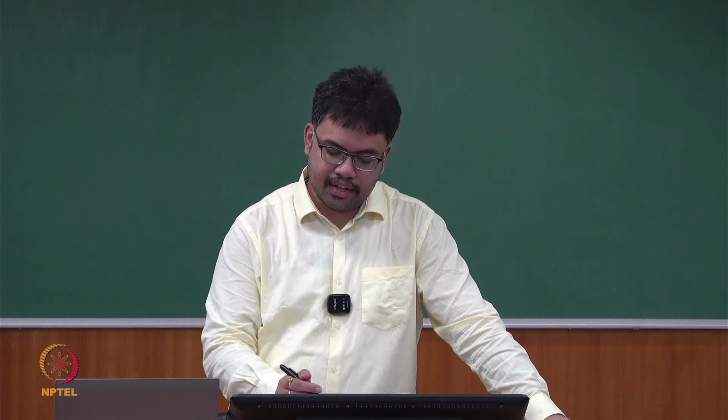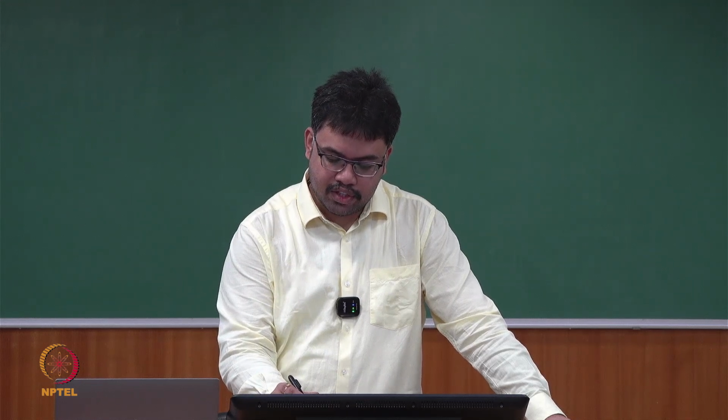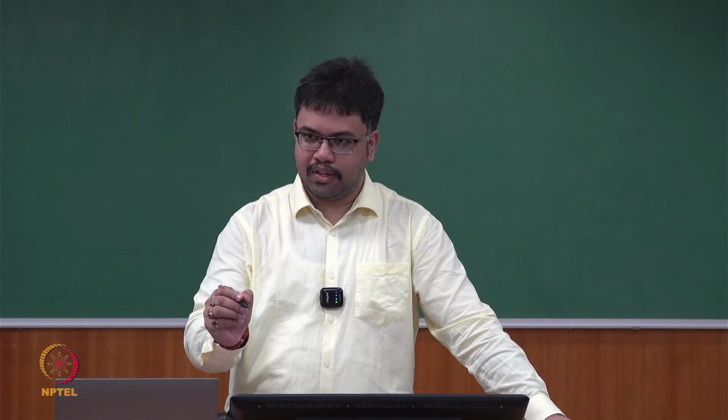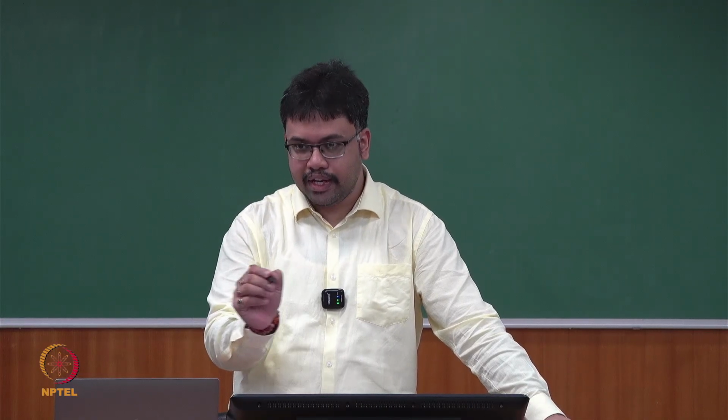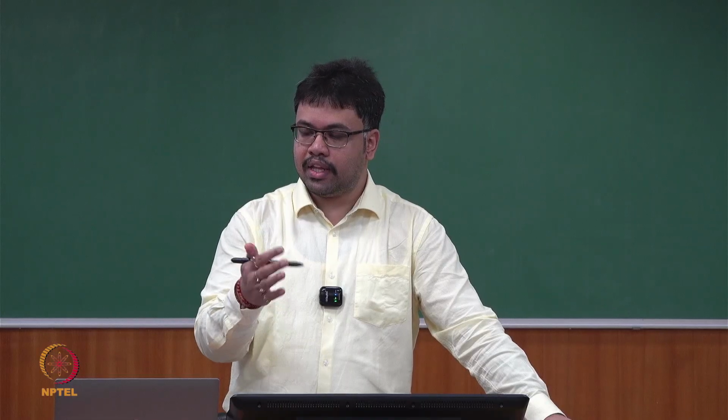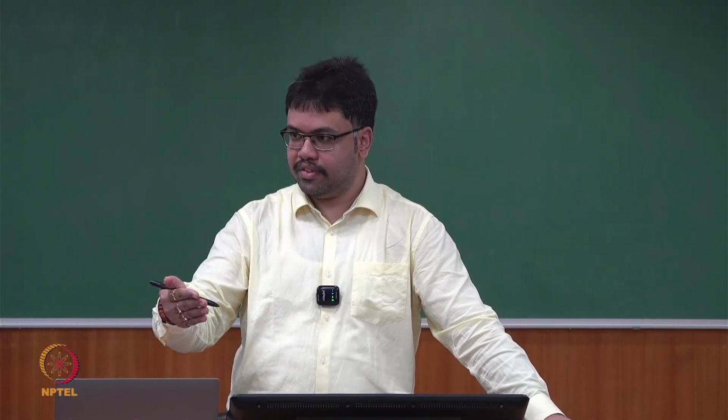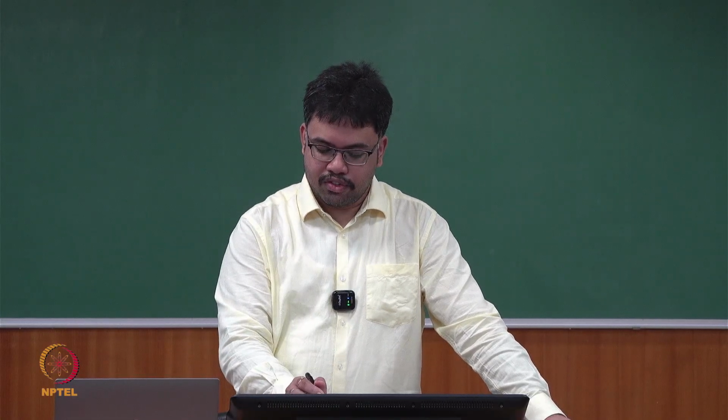So the initial velocity after the impulse, because impulse is an instantaneous process and we are not considering any time between impulse start and finish, is x0 dot equal to I by m.